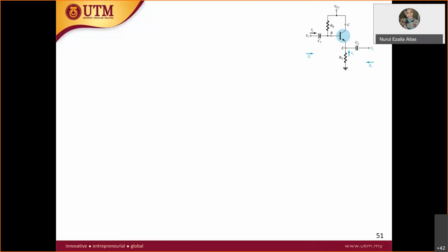So you have the circuit there. What happens to the power supply? It will go to the ground. What happens to the capacitor? It will be a short circuit. So the first thing is to draw your AC equivalent circuit.